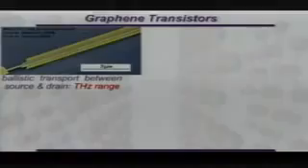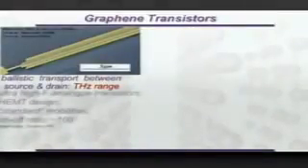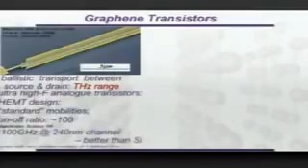The on state, when the current flows freely through the transistor, and the off state when no current goes. And graphene has the problem with the second one, so you cannot stop the current through it. It always conducts. It's not a problem for the high-frequency transistors, and many companies, including IBM, are researching it, and they are trying to get into the terahertz regime with those transistors. But it's a problem for integrated circuits applications.